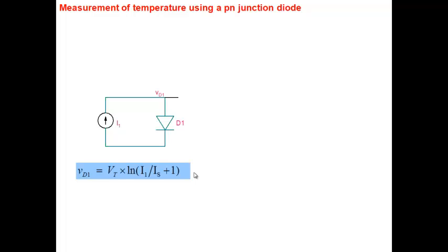So what if I do the following? I build the circuit, right? And I have an oven, and in that oven I can change the temperature from, let's say, 0 degrees to 100 degrees Celsius. So what I do is I change the temperature, I measure all of these voltages here, I keep a table, right? And then I go ahead and put that out in the sun, and whatever is the voltage, I go and read the table and tell you what the temperature is.